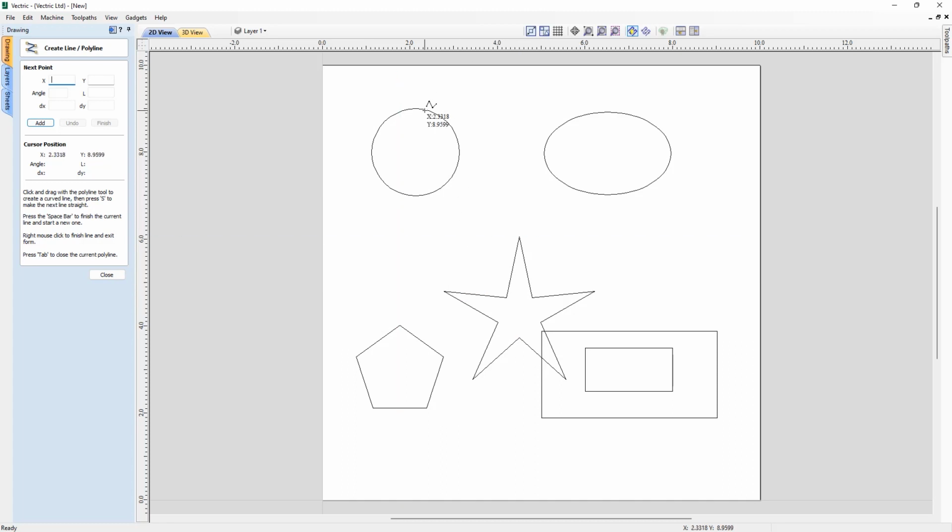In terms of our circle here, again we've got the center, we've got lots of different lines. If we start drawing here and move our cursor, take a look at the A, that's telling us the actual angle that we're going to be drawing from. Again, if we move down, you can see we've got different angles, and we are moving that in increments of 15 degrees.